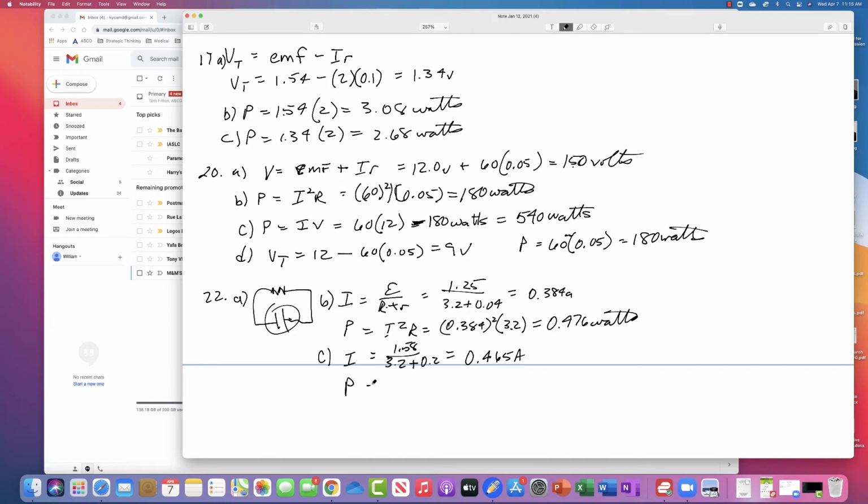And when you calculate the power using this same formula, you're going to have a higher power usage with this situation. And the higher power usage ends up being 0.691. And the last question here is, does this difference seem significant considering the effective resistance is lowered when you turn the radio up? The answer to that is if this resistance decreases, then the difference between these two decreases. And so I would say no, that it's not significant.